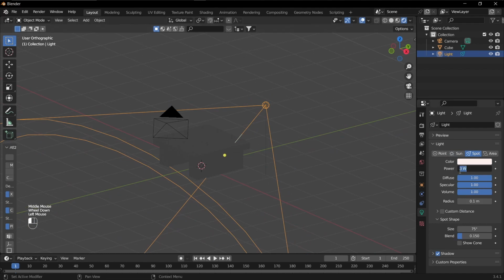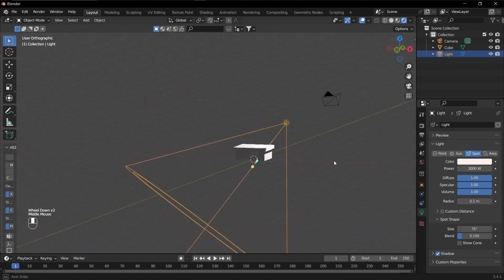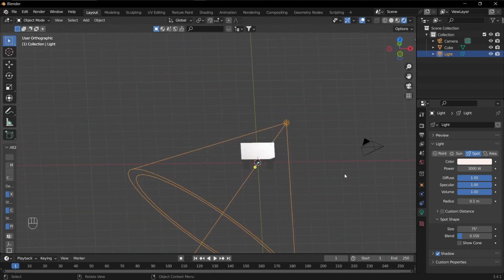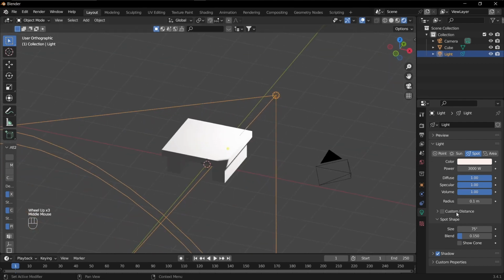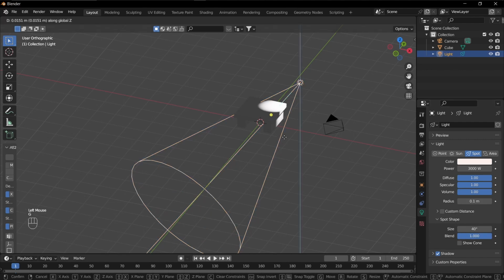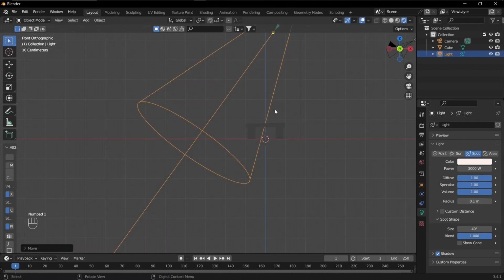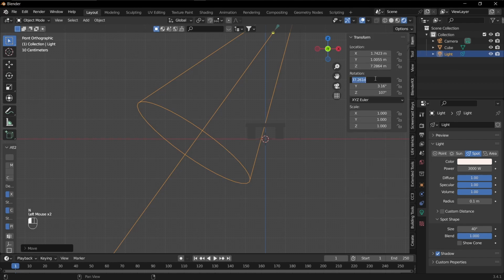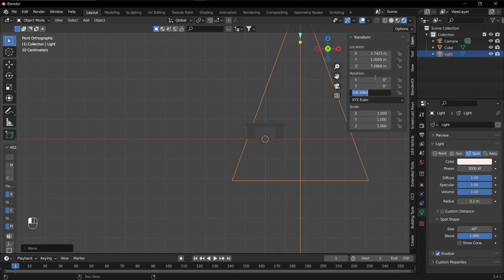Your spotlight delivers light in a cone shape, and it's directional as well. It has a radius, the size of the cone. I take this down to 40, and that affects the size of the cone. You can see it affected right there, and I can always soften it. That should soften it somehow. Just go on to height 10 and change the direction to 0, 0, and 90.